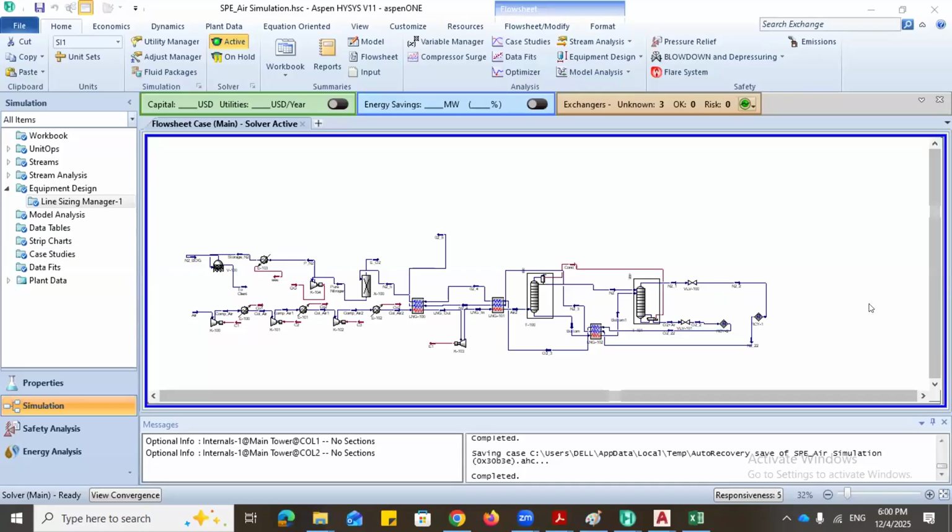Then we'll start changing the necessary equipment, shifting the equipment as per what is stated in the positioning distance. I think there's a standard that states the distance at which each equipment needs to be, as per low pressure, medium pressure, and high pressure. So everything works simultaneously. But at the detailed design, we would have completed our P&ID design and our 3D model, generated our piping ISO, and done our pipe stress analysis.